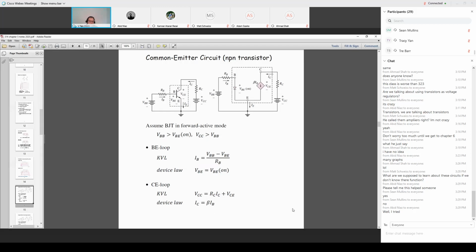So how do we model the transistor? To the left is a very abstract circuit symbol. There are 3 terminals: emitter, base, and collector. We refer to the voltage between the base and emitter as VBE, and the voltage between the collector and emitter as VCE. That's very abstract, just circuit symbol and voltage. But here we're asking, how do we model it? Because base and emitter is a PN junction, we need to forward bias it, so we model it as a PN junction diode between the base and emitter.